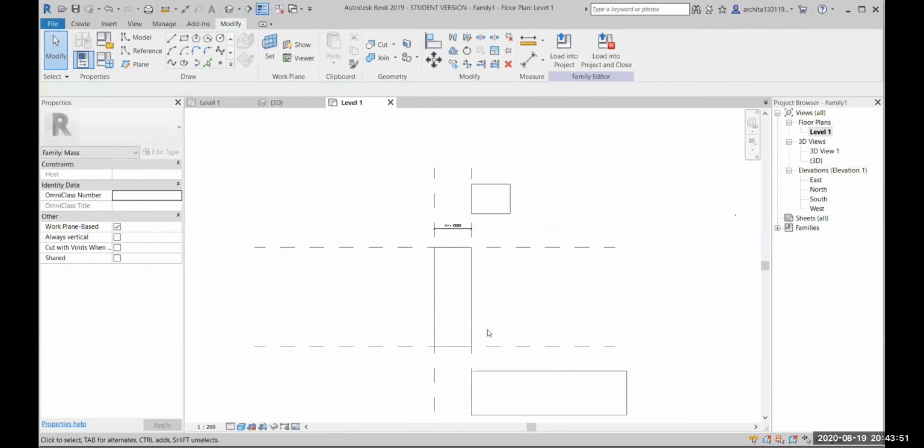Ma'am, I'm getting this constraints are not satisfied dialog box again and again. That means what is happening now, Kirtana, the locks are basically you're locking either dimensions or unnecessary items, and that's why Revit is saying that on one side you're locking the dimension also, on the other side you're asking us to move and change the dimension also. So basically there's a conflict between two constraints.